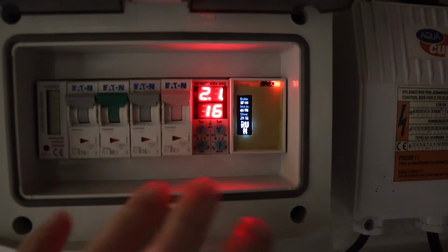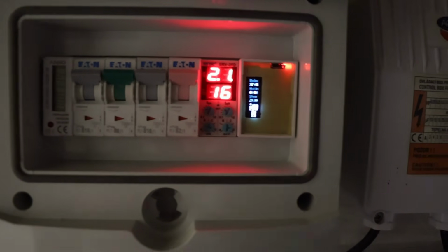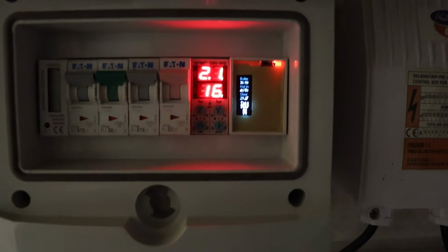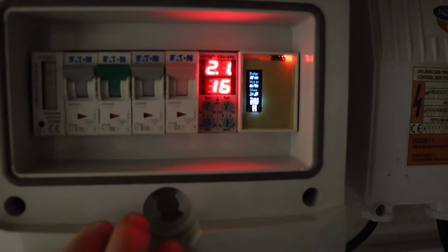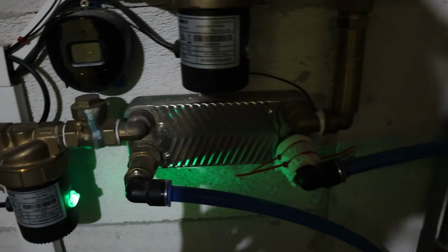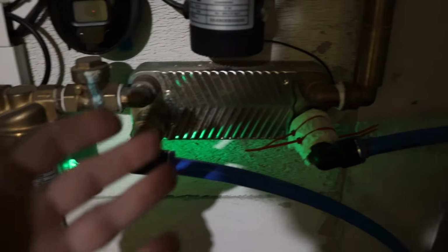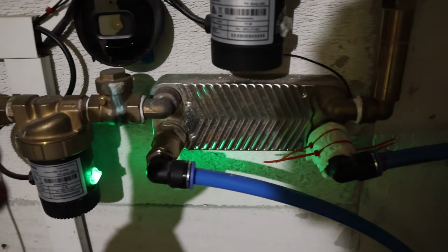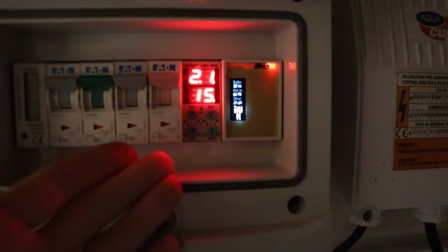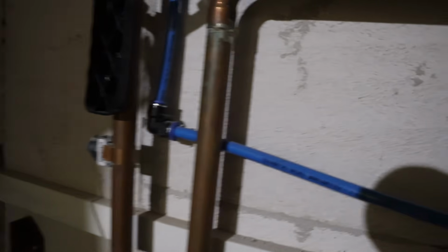Hi, I have this contraption to basically manage the boiler heating, because in the winter I am burning wood and I have some excess hot water. So I was like, okay, I can have free hot water, quote unquote, with this heat exchanger, but I want to somehow control how it works. Obviously you don't want a situation where you have a boiler heated up to 60 degrees, then suddenly you start pumping the water through the boiler through the exchanger when you start heating your house.